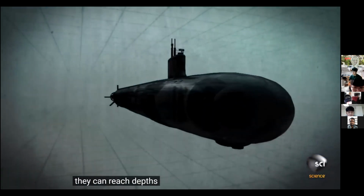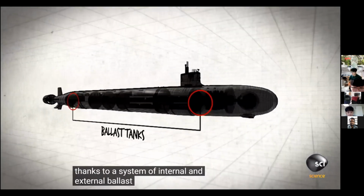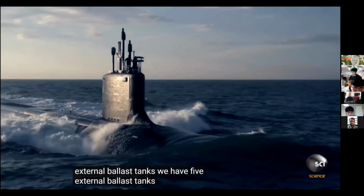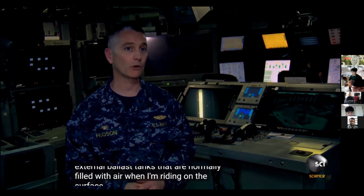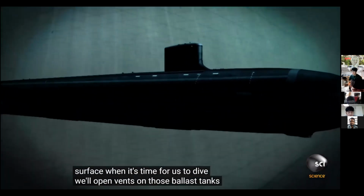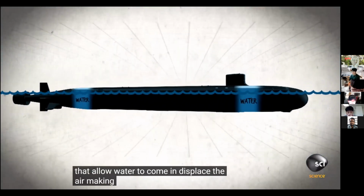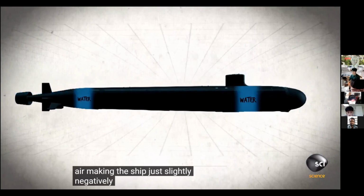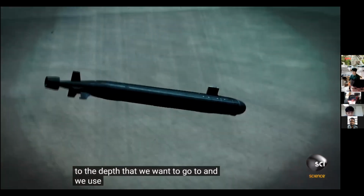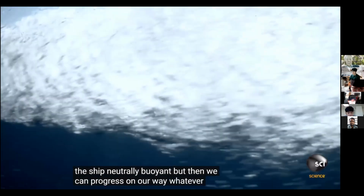They can reach depths of about 800 feet thanks to a system of internal and external ballast tanks. We have 5 external ballast tanks that are normally filled with air when I'm riding on the surface. When it is time for us to dive, we'll open vents on those ballast tanks. There's grates on the bottom of the ship that allow water to come in, displace the air, making the ship just slightly negatively buoyant. We then proceed down to the depth that we want to go to. And we use internal ballast tanks to make the ship neutrally buoyant, that then we can progress on our way in whatever depth we choose.